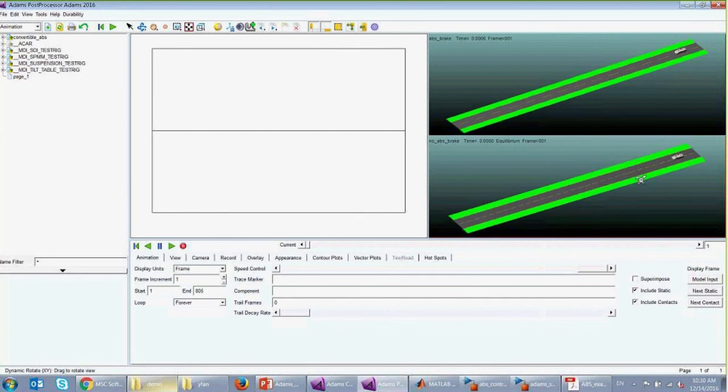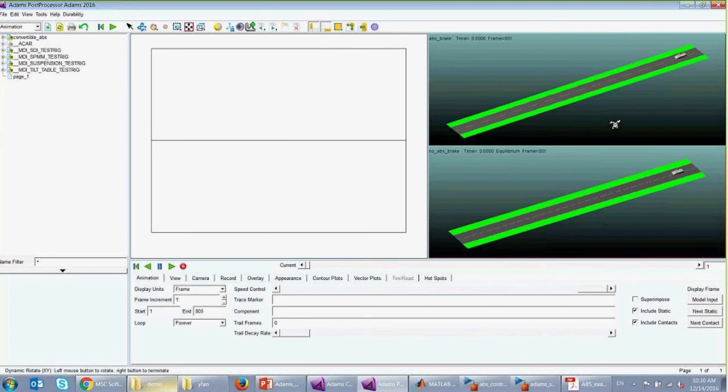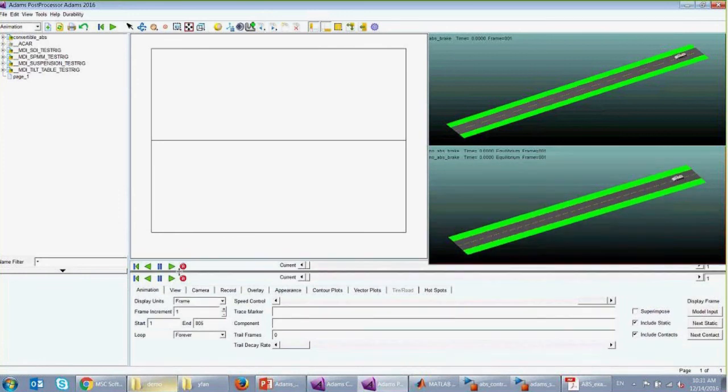And as we know from experience, if the ABS system is activated, it's going to take a longer distance to bring the vehicle to a stop, but you can keep maintaining the direction of your vehicle, and the steering is still going to be effective. But in the event when there is no ABS brake and the road is slippery, and the friction ratio on the left side of the road is different from the right side, you will see the spinning effect of your vehicle.